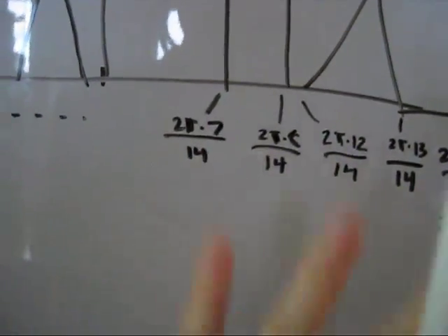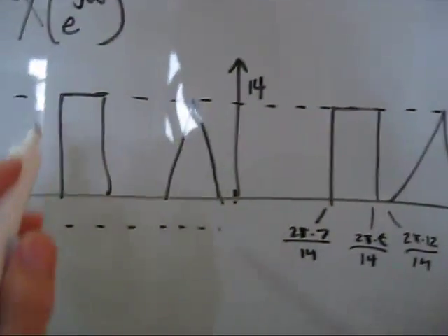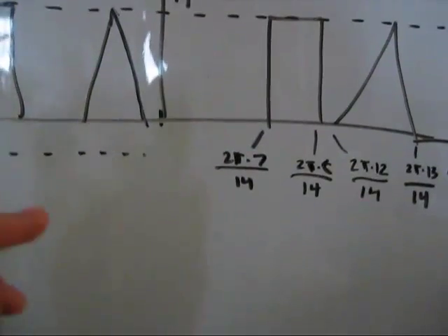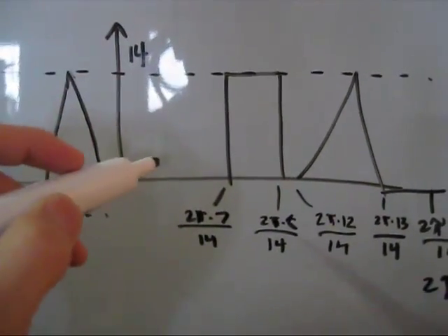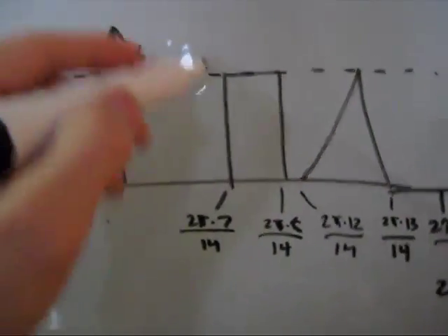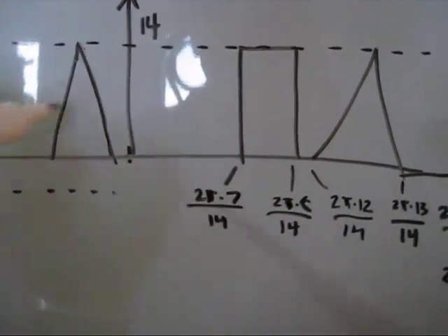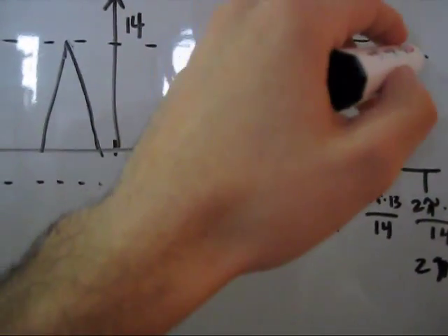Okay, with me so far? You go back out at 14 hertz, and you're going to have an output whose spectrum looks like both of these, right? Both of them. So what we do instead is filter out these lower frequency parts by only passing through the high frequency parts.